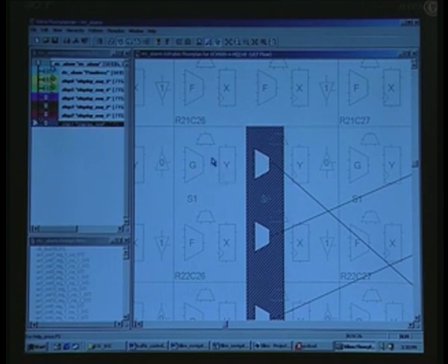I am not sure whether you can see on the TV monitor there, and you have 4 input muxes here, 4 of them are there, and 4 flip flops are there. It may have Q bar, then preset, clock input, all are available, and in addition to that 4 2-input muxes are also there. So, you can call this one logic block, or I do not know really what the Xilinx terminology is,